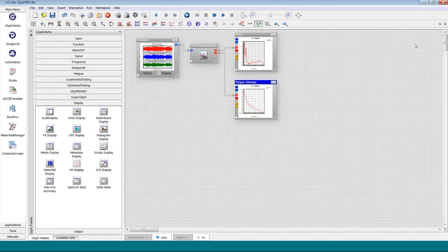So what I've done so far is quantified the severity of mission or measured data in two ways, in terms of shock and in terms of damage. If the part is designed solely with durability in mind, the fatigue damage spectrum is very important. If it is designed solely with shock in mind, then this is very important. This is your iPhone, for example. It's designed to be shocked, dropped, or abused a few times, but as I said earlier, shame on you if you expect to drop it 1,000 times and continue to work.